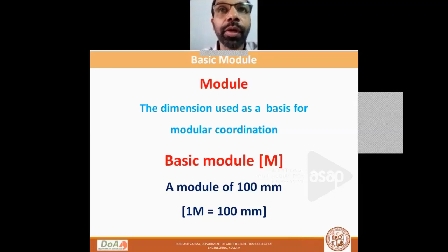I'll tell you the example of the design of Indian temples, where the dimension, the width of the prasada or the sanctum sanctorum, becomes the basic module, and the entire complex is planned on the basis of the grid developed with this size as the basic module. And this basic module in traditional architecture is known as the dand.